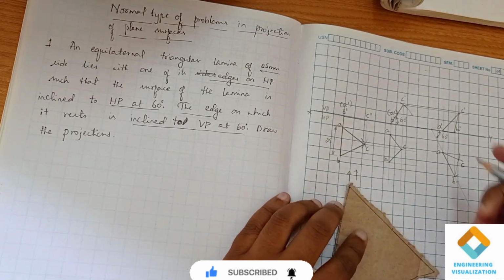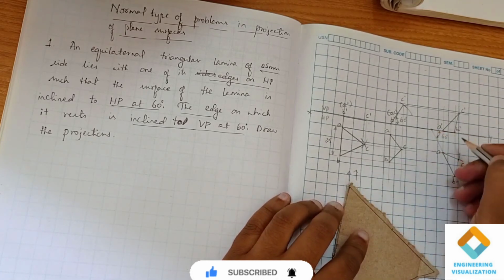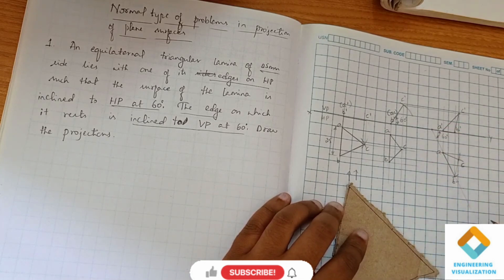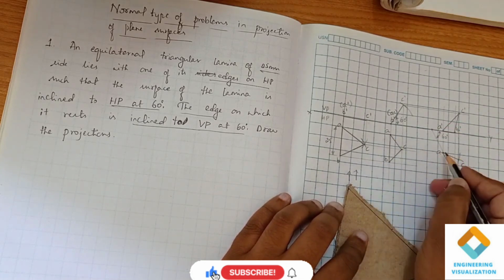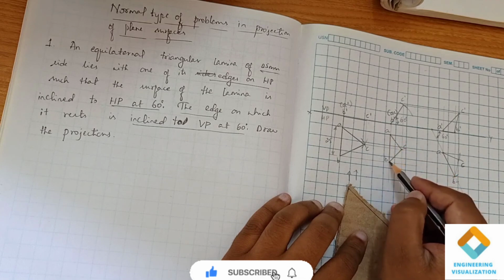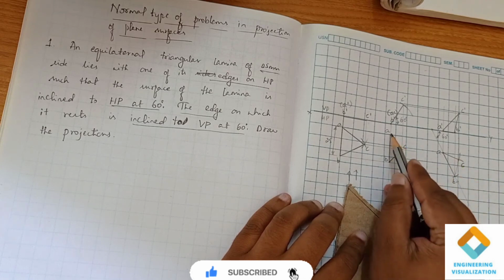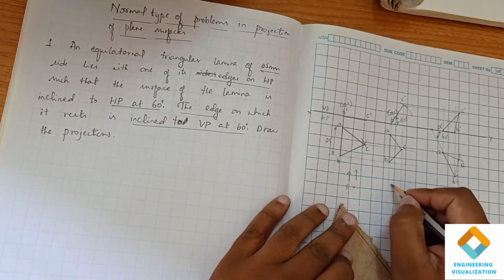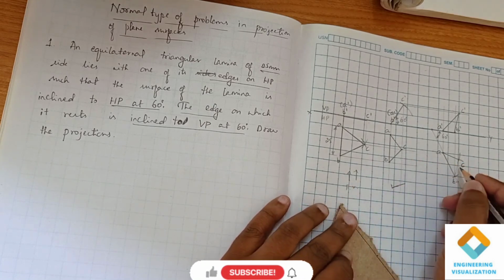So for that purpose, first we mark a reference point, then we use the protractor, mark 60 degrees, and then we draw an angle line. Then after that we mark a reference point A. Next, from the compass we measure the length of AB and cut the arc. Then again we draw arcs from A to C and B to C. We have completed the diagram. So this diagram we have used for copying here.